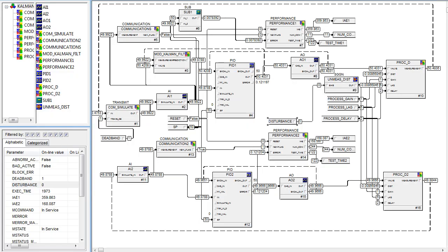If we examine then the performance, we notice again that the wireless control is a little bit worse than the wired control. However, in this case, it only took 11 new communicated values for our wireless control versus over 200 communicated values used in our wired control.